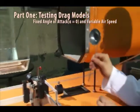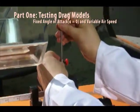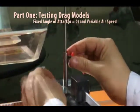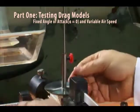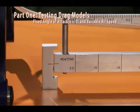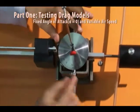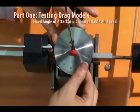Select the drag model and open the test section in the wind tunnel. Mount the required drag model in the lift and drag balance. Make sure that the balance is at the null position. Also make sure that the angle of attack is 0 on the protractor for all tests in Part 1.